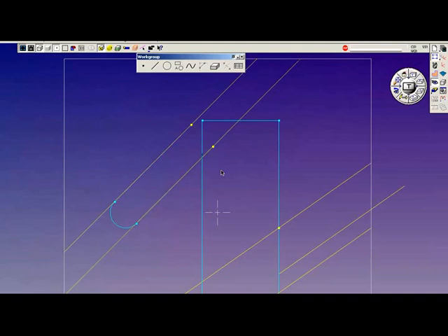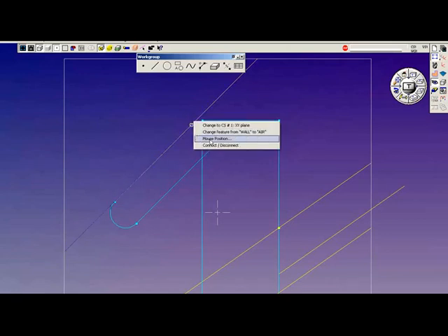Terminators are generated the same way as connectors. Control click the line and the point and connect. Or, like the previous method, shift window the point and the line, right mouse click, connect. This is now an open terminated feature. My cutter will start anywhere I like outside the feature, come inside, and come out to anywhere I specify on the cut as it leaves the feature.